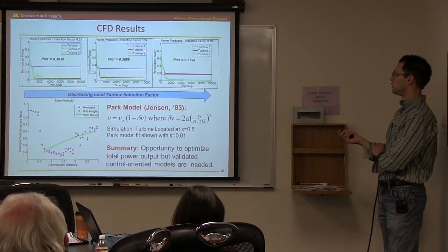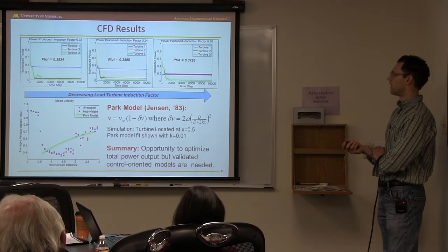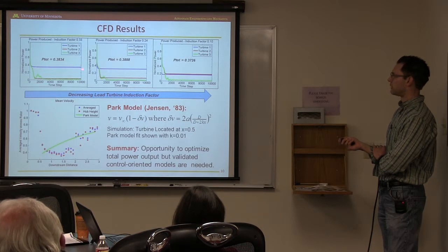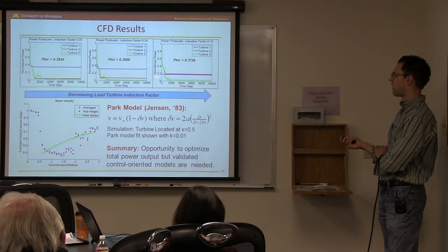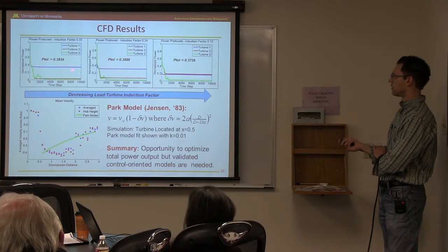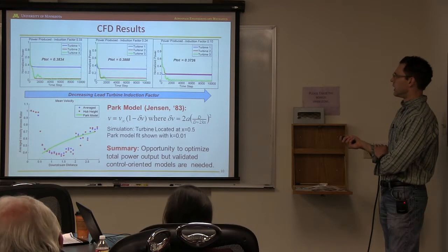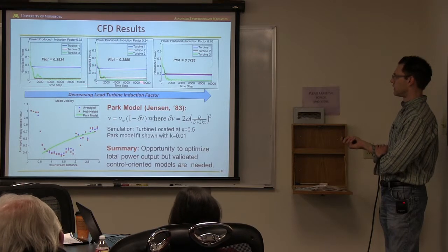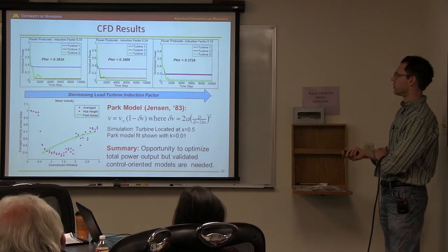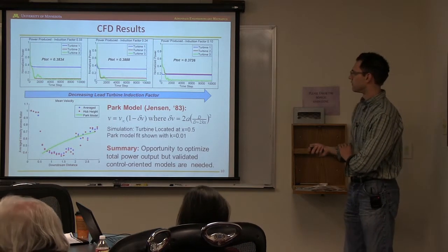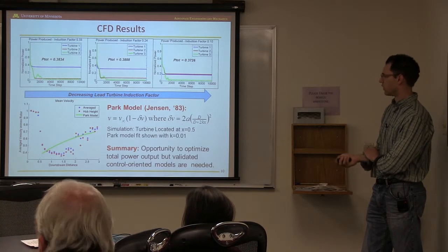And then in the next 2, you derate the first turbine. You make the first turbine generate less power than it could if it was operating optimally. So if you look at the blue curve, this is the power generated by the first turbine. You notice the blue curve is dropping in each plot. You're generating less power from the first turbine. But if you look at the second turbine, which is the red, it's generating more power as you go along this direction. And then if you look at just the net power in the steady state, you're actually getting more power output by derating the first turbine. So I think there've been several papers of this kind of nature, and this is just a CFD simulation showing this kind of behavior. And so that's something that we're trying to look at.